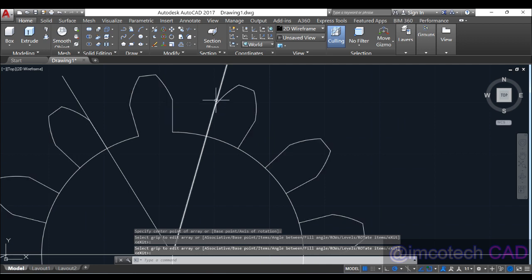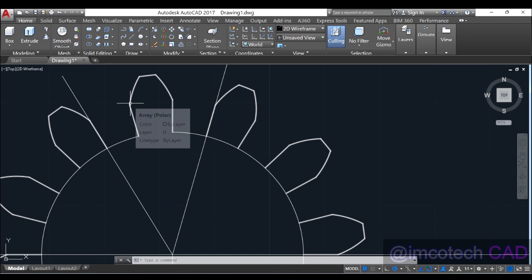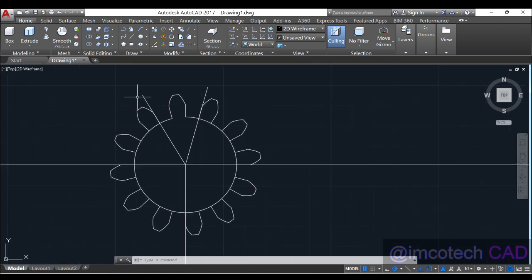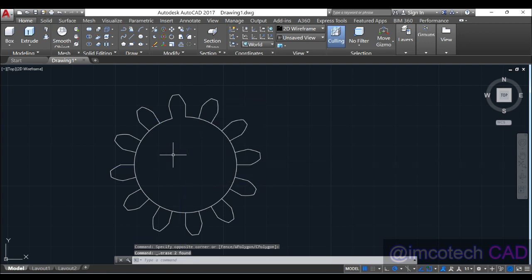Look, from this corresponding side to the other side is one circular pitch. So the tooth thickness is circular pitch over 2. That is, from this place to this place, CP over 2. Although that would be an arc, right? It will be an arc. But if you ask for the chordal length, it will be a straight line to that point, which is a chord, right? So this can be gone actually, and this should be gone.